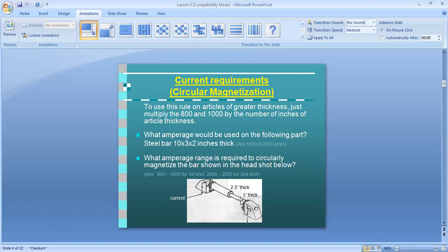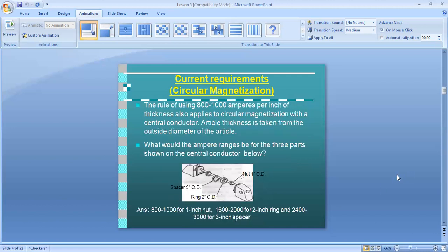Okay, so here there is no meaning to check, because we know there is no discontinuity, but because of excess current, the field leakage chances will increase, and you will see the indication. But there are no physical discontinuities present there. Now this is the central conductor technique.